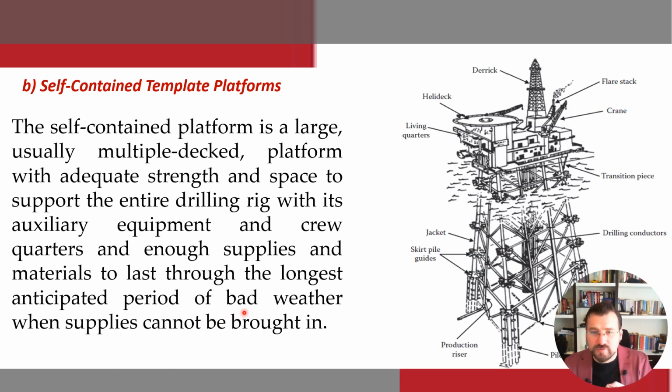Another one is the self-contained template platforms. The self-contained platform is a large, usually multiple-decked platform with adequate strength and space to support the entire drilling rig with its auxiliary equipment and crew quarters and enough supplies and materials to last through the longest anticipated period of bad weather when supplies cannot be brought in.